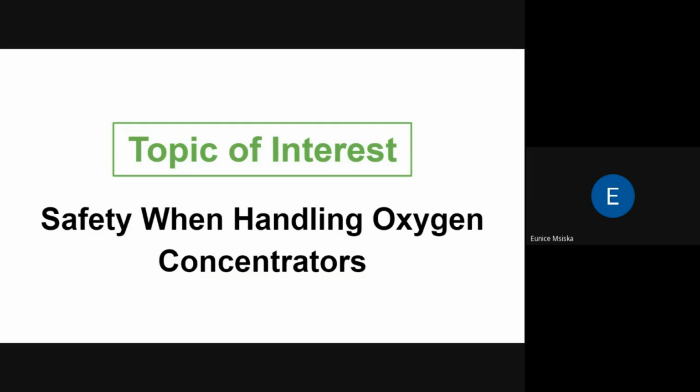So if the valves are not switching properly, sometimes maybe only one segment can be fed with ambient air, or the other one is not fed, and that can lead to low oxygen purity. So if there is low purity, please troubleshoot and fix all the problems that are causing the low oxygen purity.